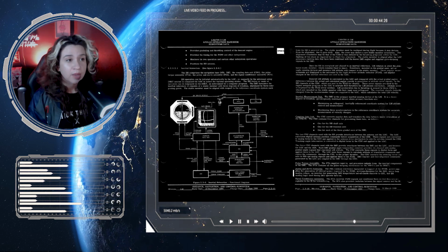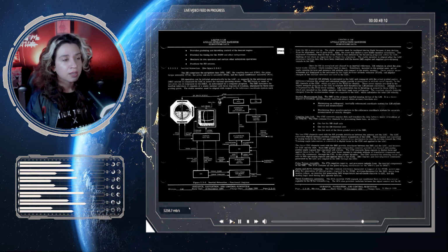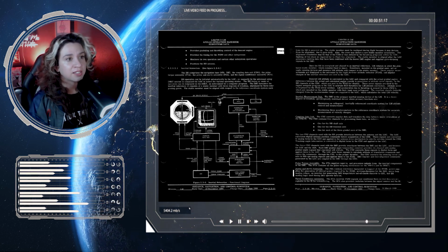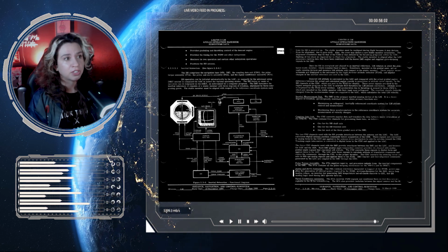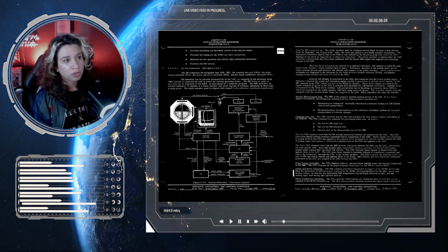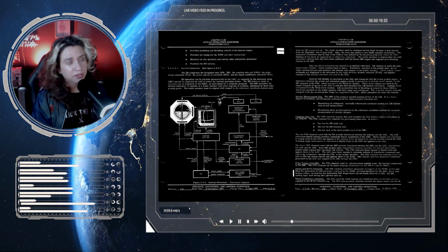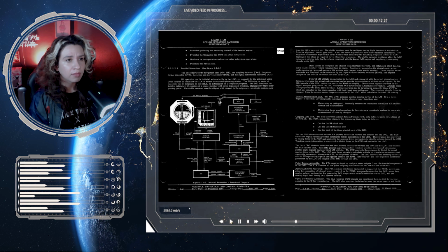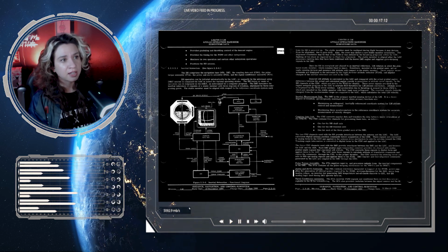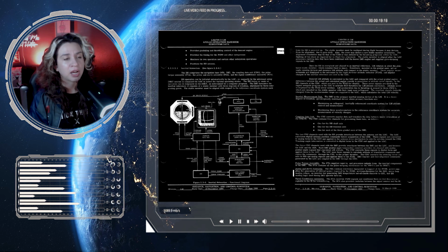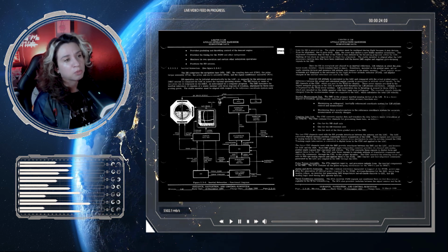Also, the crew may desire a new stable member orientation. The alignment orientation may be that of the CSM or that defined by the thrusting programs within the LGC. Sightings of 2 stars are required for in-flight fine alignment. The stable member is aligned after the LGC processes sighting data that may have been combined with the known IMU angles and supplies gyro torquing signals to the IMU.